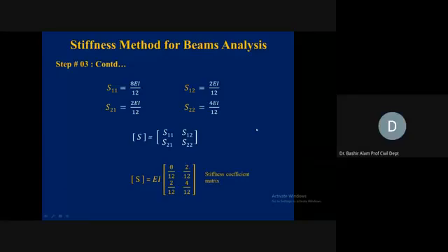Because of the time constraints. So, the stiffness matrix now you write at a location. Very clearly, in step number 1, we found the AD matrix, and that was coupled, remember, with the labeling of the D's, the unknown joint displacements. Those D's are becoming our reference, actually the baseline.